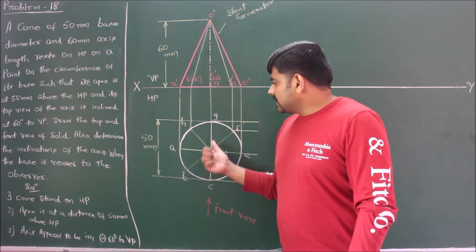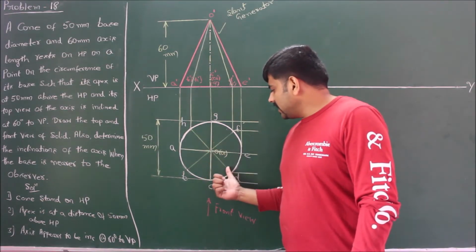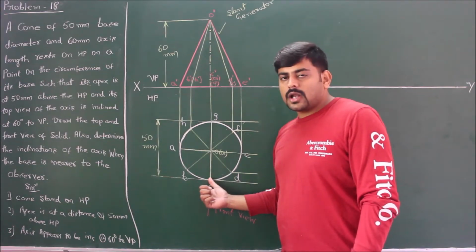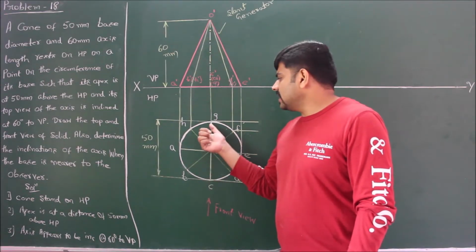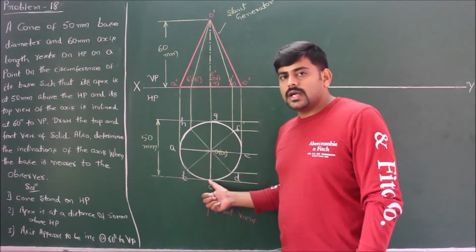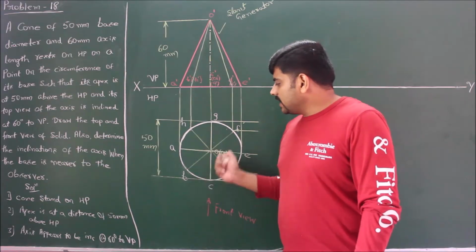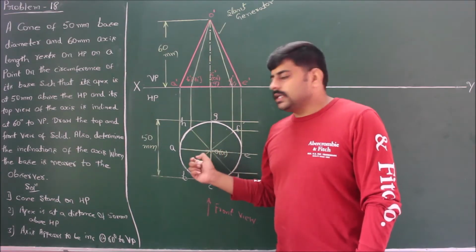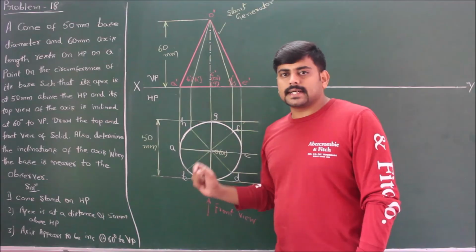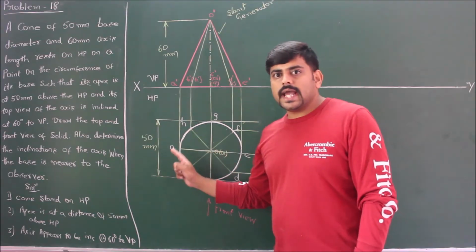That is, I have measured from the vertical point G 45 degrees, 90 degrees, 135 degrees and 180 degrees clockwise. Again from the vertical, I have measured 45 degrees, 90 degrees, 135 degrees and 180 degrees counterclockwise, and joining the lines, I divided the circle into 8 sectors. Now mark the points on the circumference. You will get 8 points.